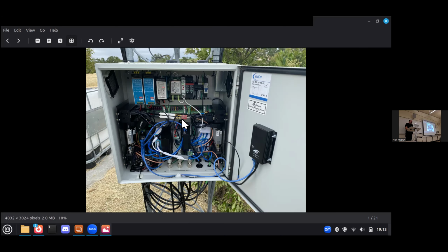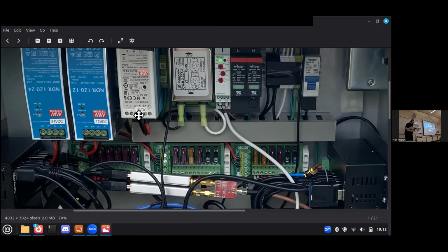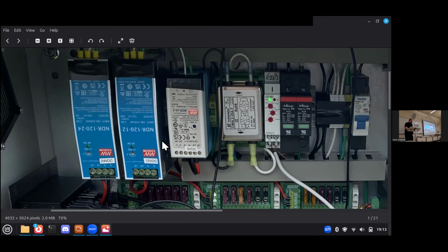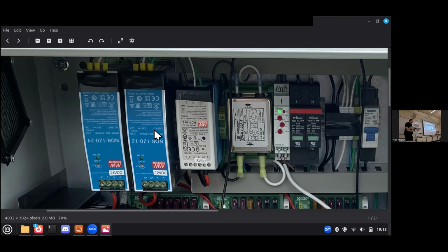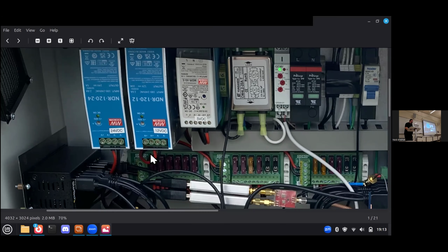Can we please talk about the power supplies? Yep. They are also DIN rail. These are just Meanwell AC to DC switching power supplies that are DIN rail mount. So the AC power goes in the top, DC comes out at the bottom. Technically the other way around. I flip them around, but they work either right side up or upside down. The manual said that was fine.